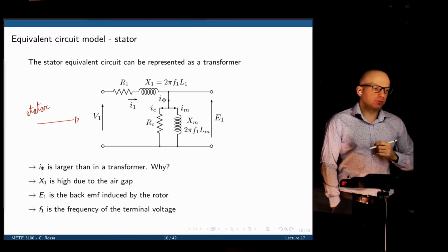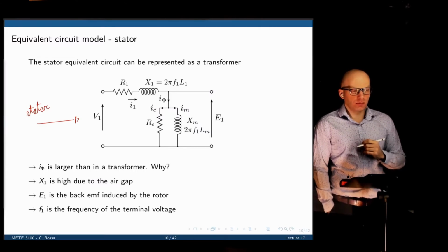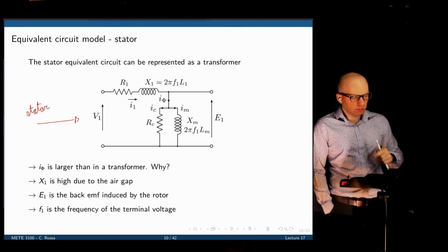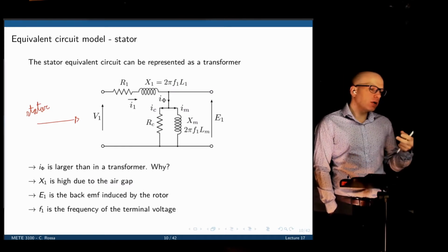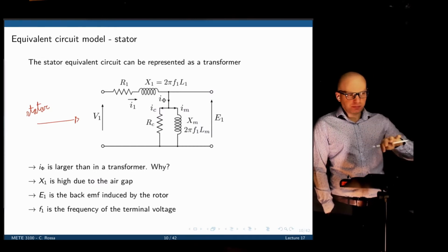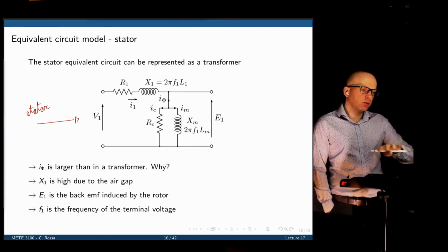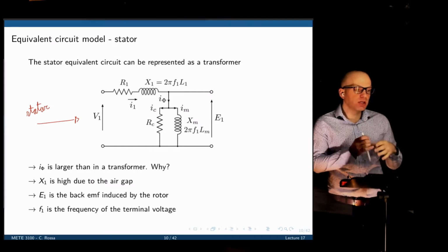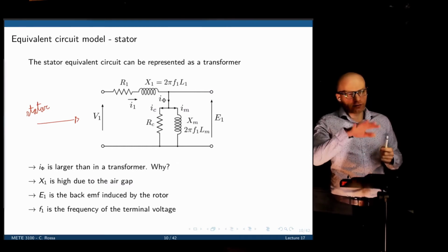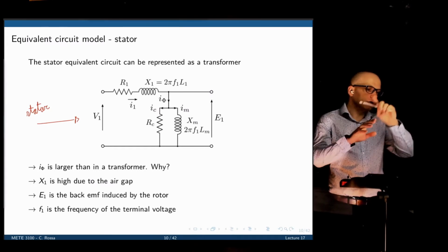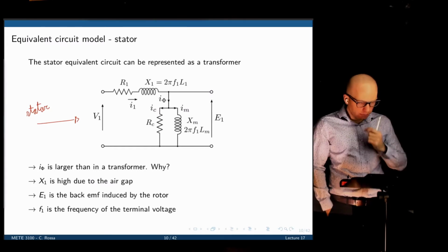When designing induction motors, if I just increase the number of coils in the stator, would that decrease the air gap, because there's less of an air gap for the rotor to rotate to hit the next coil? Yes, that's a very good point. You put as many coils as you can to make a more uniform magnetic field and minimize the need to magnetize a large area. So you will see in an induction machine, the ones that I've been using here have three coils, but one phase can have multiple coils distributed in space. Okay, thank you.